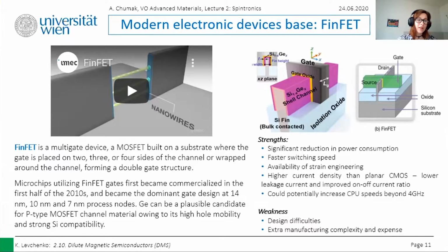It's a FinFET, or multi-gate device. We already reviewed how it compares to the traditional planar transistors and what the advantages and disadvantages are. Just a few words. In a traditional 2D planar transistor, a conductive channel is formed in a silicon region under the gate.